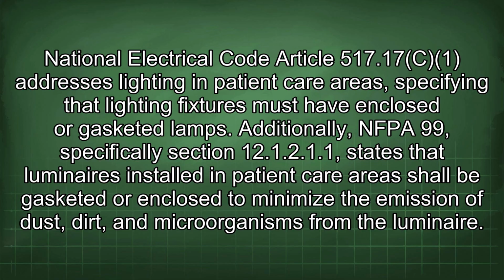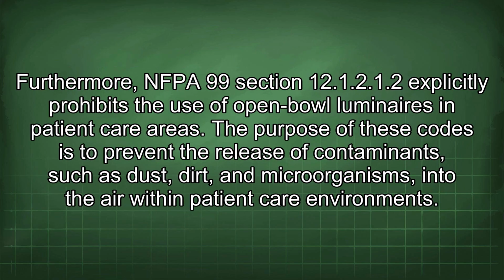Additionally, NFPA 99, specifically Section 12.1.2.11, states that luminaires installed in patient care areas shall be gasketed or enclosed to minimize the emission of dust, dirt, and microorganisms from the luminaire. Furthermore, NFPA 99 Section 12.1.2.12 explicitly prohibits the use of open ball luminaires in patient care areas.